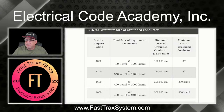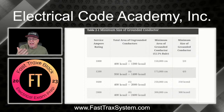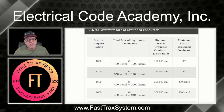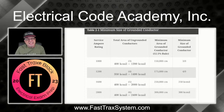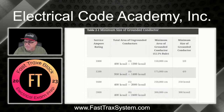And if I decided, because I want to go with smaller conductors for that same service, maybe now I want to get a 1,200 amp service, or maybe I want to run 4 sets of 350 kcmil. Well, 350 times 4 is 1,400,000 circular mils, or 1,400 kcmil. And you just simply take that and multiply that by 12.5%, and that's where you get the 175,000.